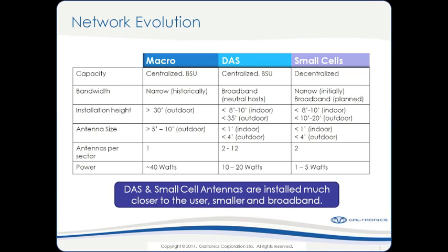And now when we look at small cells, we'll see that we have 2 antennas per sector, and each small cell in fact represents or can be thought of as its own sector. So the 2 antennas here would be for a main and a diversity antenna in a 3G small cell application, or a MIMO path A and a MIMO path B antenna in an LTE MIMO configuration. And again, because the small cells can be considered as their own sector, we need to be very concerned about controlling the coverage and making sure we manage these cell edge and hard handover regions in space.